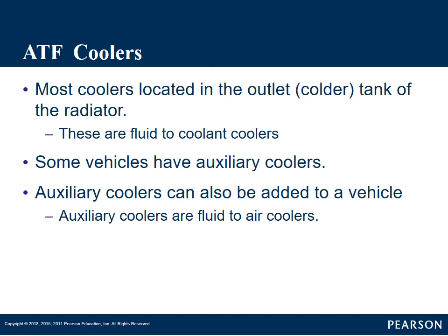Some of the ways they mount these is kind of two ways when they have both of those. They'll have it to where it goes through the radiator, then into the air cooler, then back to the transmission. Most of them will run it through the air cooler, then through the radiator, then back to the transmission.